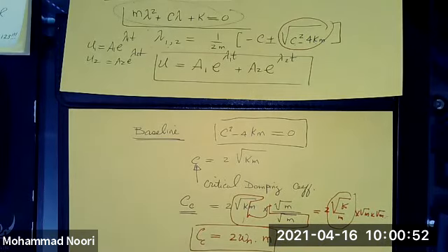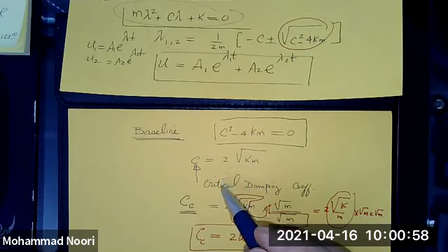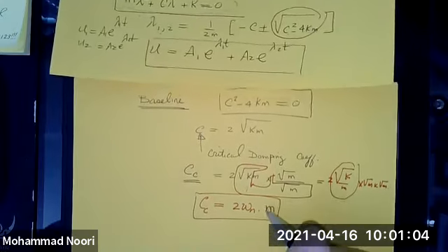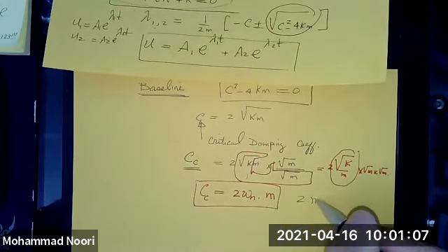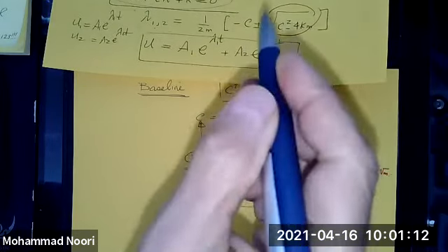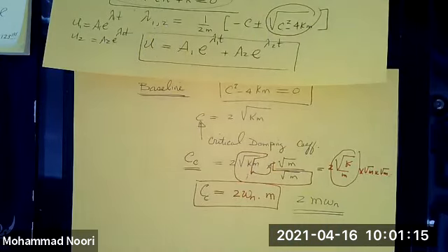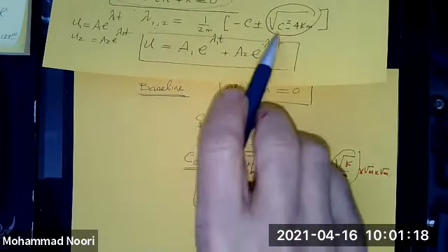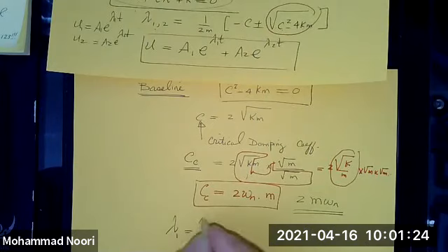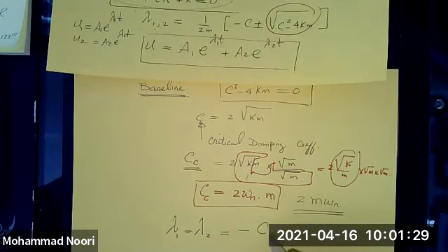So if the value of damping in a system is equal to the critical damping, we demonstrated that it is equal to 2 times mass times the natural frequency of the system. So in the case that the solution of this differential equation is such that we have this equal to 0, the two roots would be equal and will be minus C sub c divided by 2m.